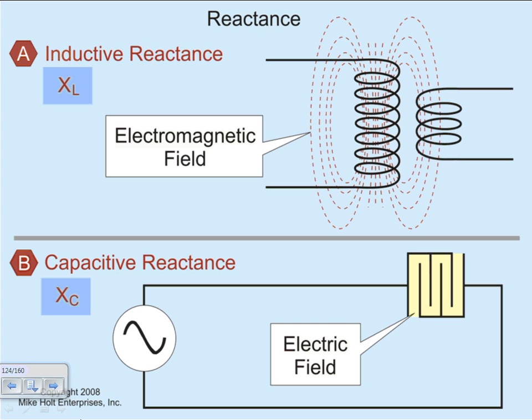A lower power factor means if you take 100 amps from Excel Energy, and your power factor is 70%, you are only using 70 amps. What happened to the rest of the 30 amps? It's almost lost, sitting there magnetizing your system. So think of it from an Excel Energy point of view. They are giving you a wire and a transformer and a relay and all this stuff to give you 100 amps, and because of your bad power factor in your building, you decided to take that 100 amps and only use 70 of it.